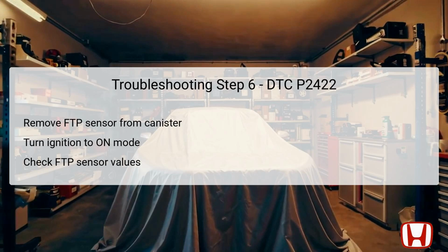If the condition is within thresholds, then the issue may lie within the EVAP canister itself, necessitating a replacement to rectify internal blockages. Conversely, if the sensor values do not meet the required thresholds, the recommendation would be to replace the FTP sensor to ensure optimal system functionality.